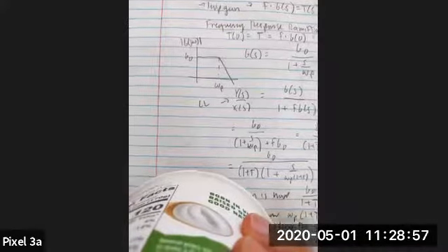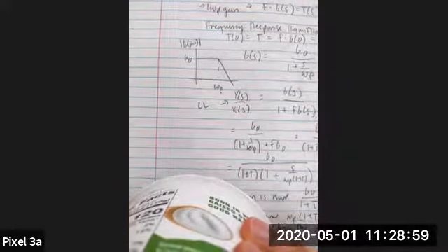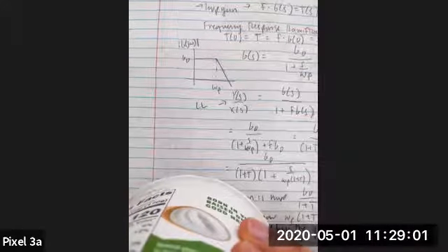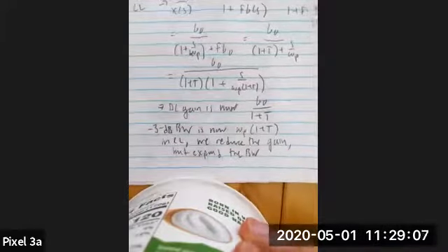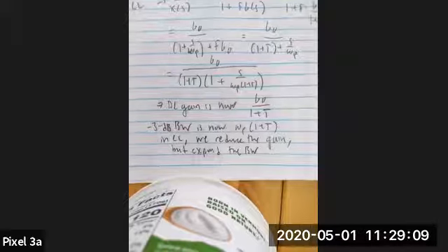as we see there. And you would have seen this in the lab if we had gotten to do that in person. But omega p won't be so large, but G naught might be large. And so this technique, by putting it in feedback, allows us to possibly extend the bandwidth just via the feedback while cutting our gain.